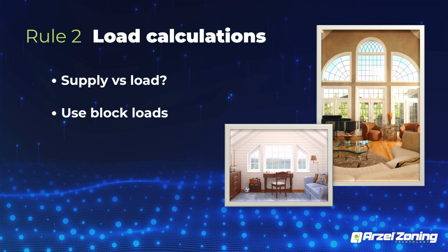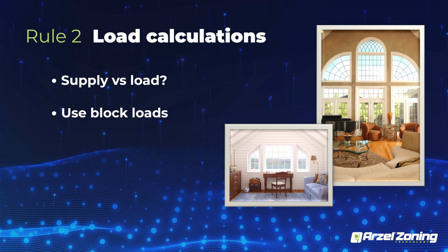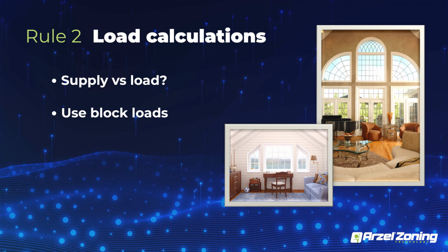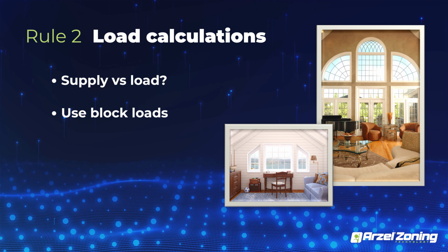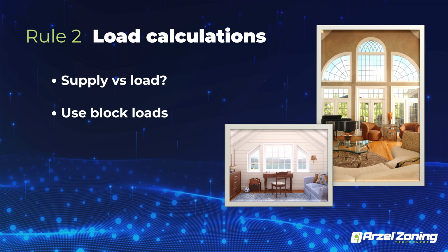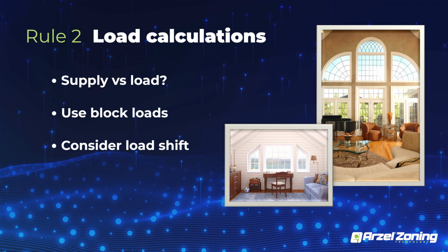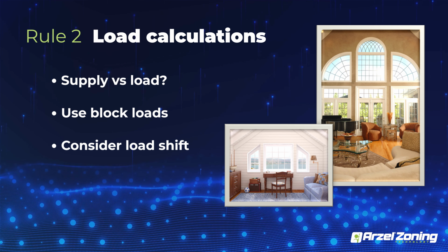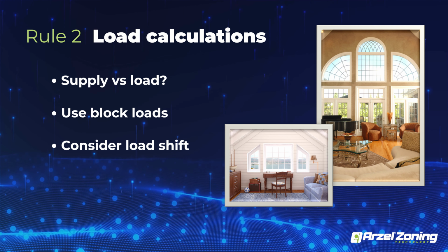If you have a home that you guys built and put the system in, and you have a history, or you've done the change out, and historically this system works great, they just suffer from physics. Warm air rises, cold air falls. First floor is great because that's where the thermostat is at, and the thermostat doesn't know it's getting too warm on the second floor. Apply zoning to it.